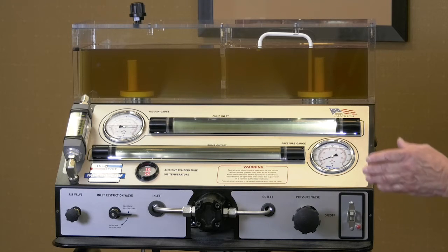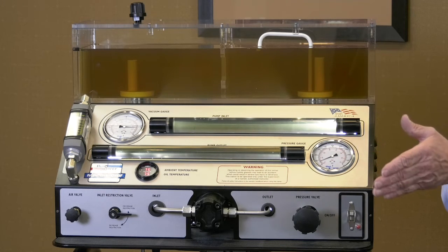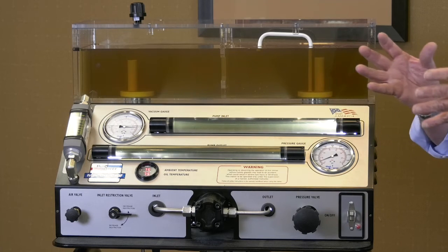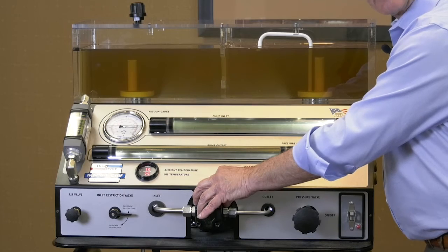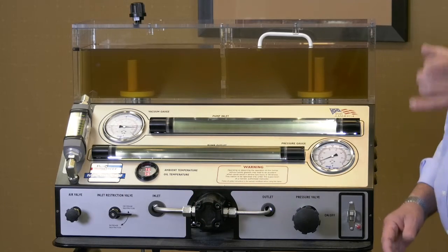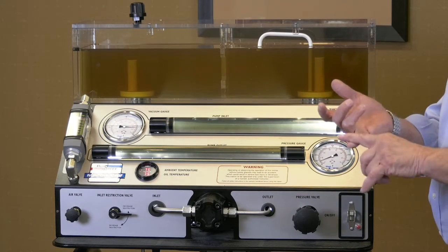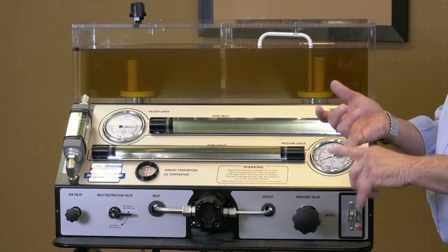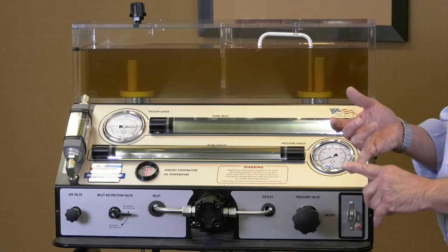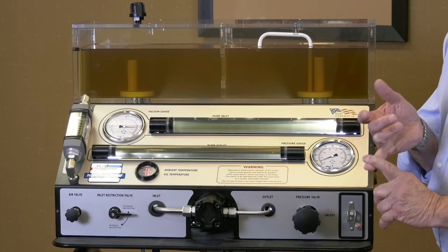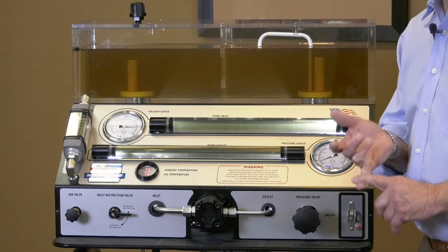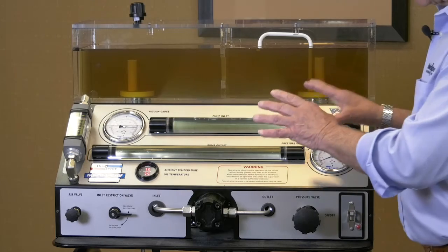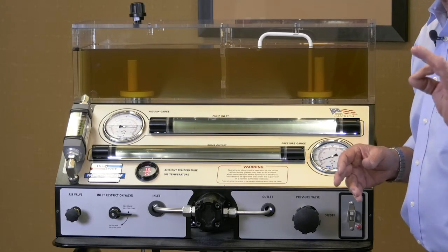Now, let me just remind you, this is a 1.8 gallon per minute gear pump. Maximum inlet restriction, by the manufacturer's specification, is 8 inches of mercury at normal operating temperature. I have 5 inches of mercury, which is this particular hydraulic system's point of reference.